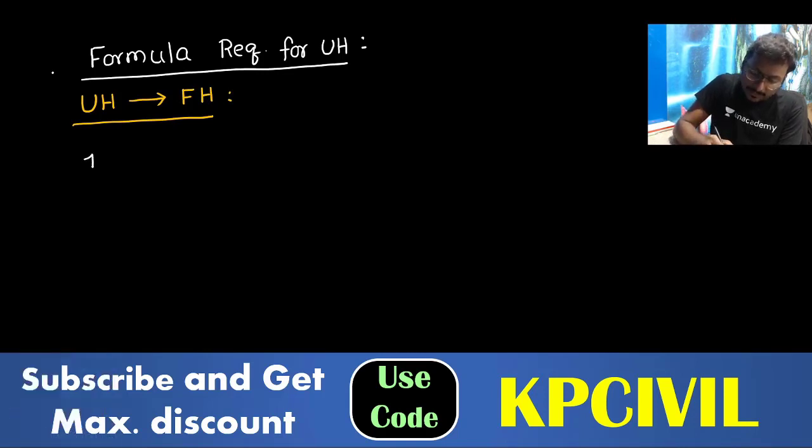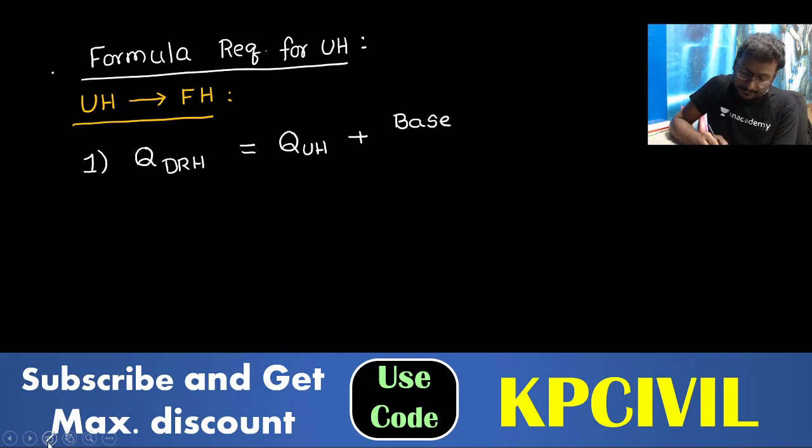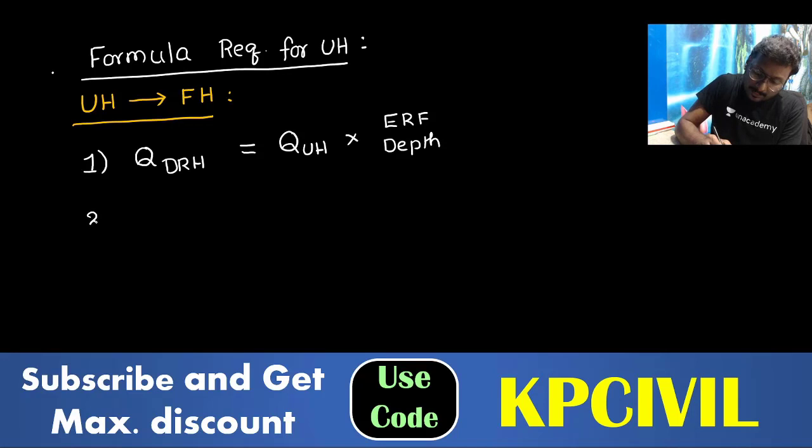So the first formula: QDRH, direct runoff hydrograph discharge, is equal to QUH into effective rainfall depth. And QFH, how will you get QFH?